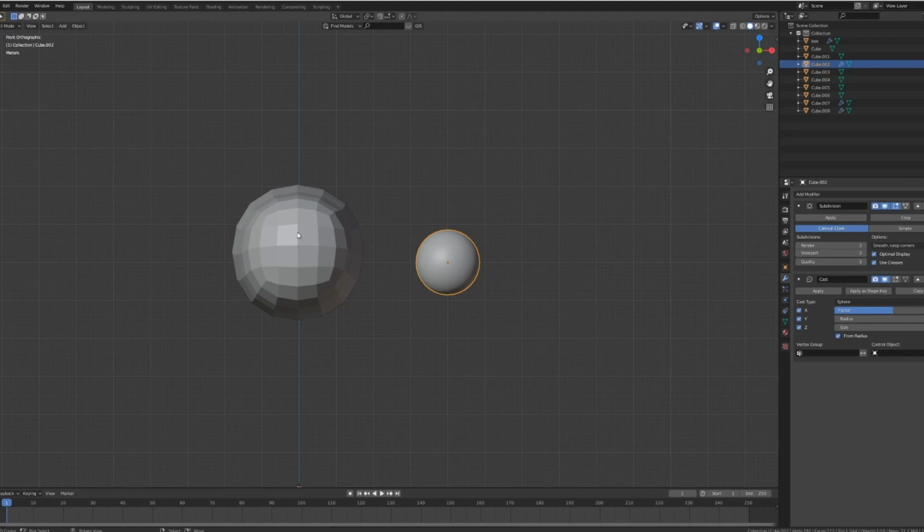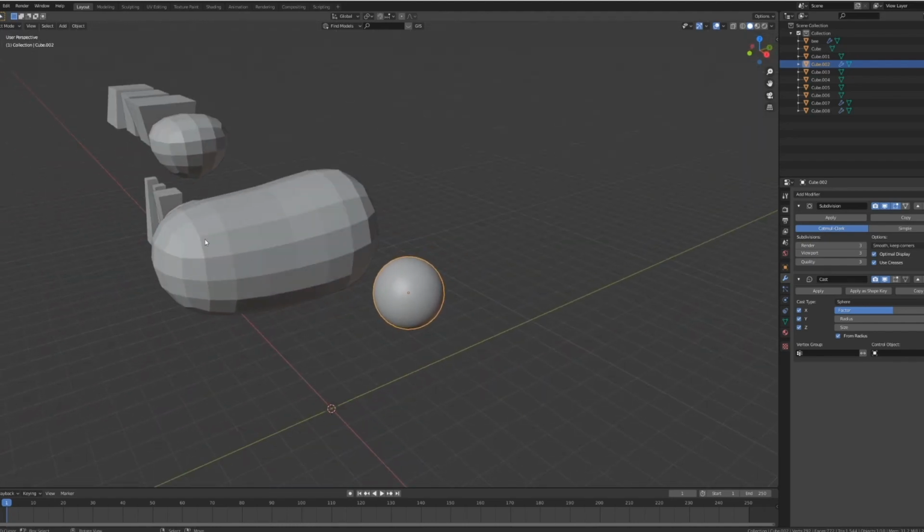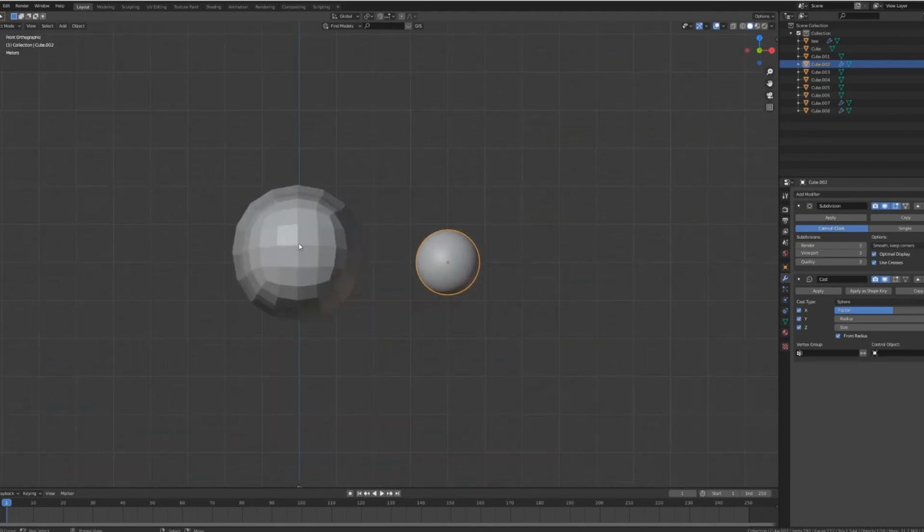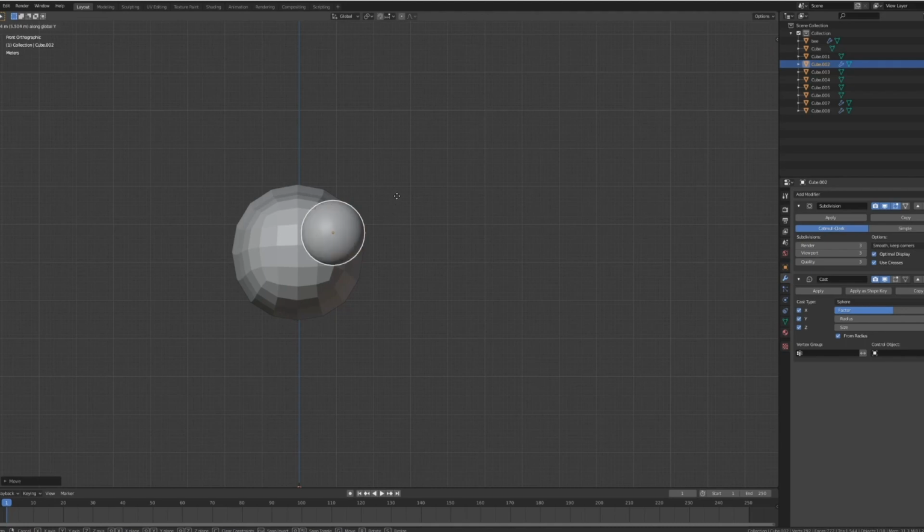What I usually do is I select a mid position and then I do a bigger eye and a smaller eye. Now always do it in reference to the model. So for example, if this is, let's say, our bee, I try to look where the eyes are just too big to create a normal expression. I just press S to scale and then hold Control and start scaling it down until a point where it's almost like organic, where it almost feels like it's an organic eye. Now, when I have that shape, that's going to be my mid position shape.